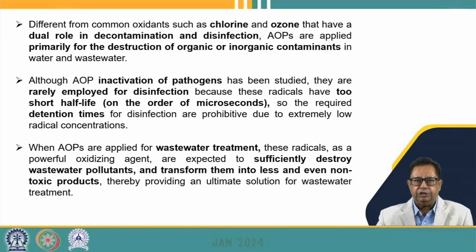It has been studied earlier that AOPs can be used for inactivation of pathogens, but they are rarely used for disinfection because they have a very short half-life, of the order of microseconds. A huge detention time may be required for disinfection, and that's why they are not used for the inactivation of pathogens.